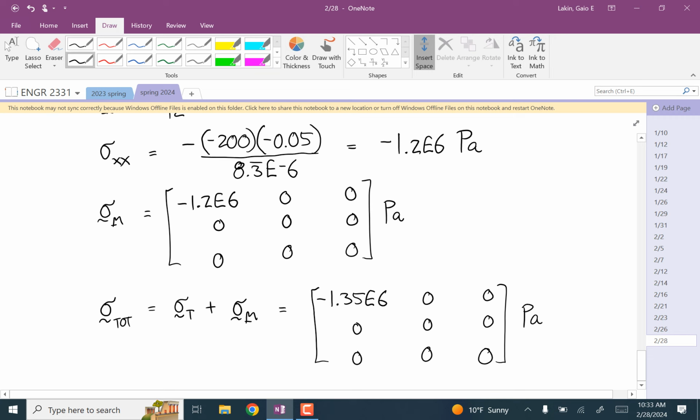Okay? Yeah. Will we ever, in a 2D, will we ever have to worry about a stress tensor because of the moment in any other direction other than X? Moment is only in the X direction, but the torque and the shear force are gonna give shear stresses. Yeah. So we will see shear stresses, but these two things are just always going to be in X.